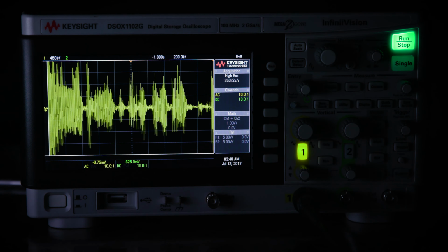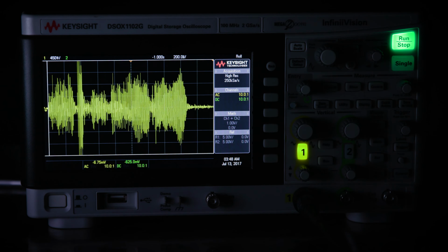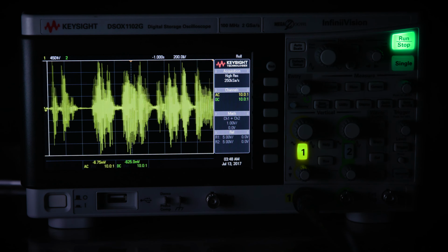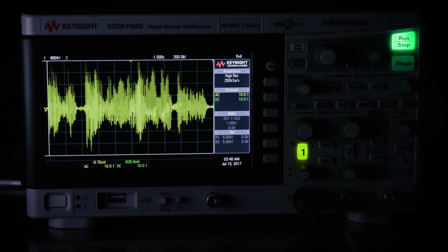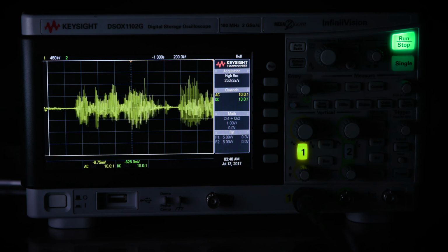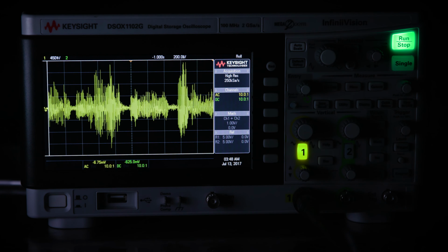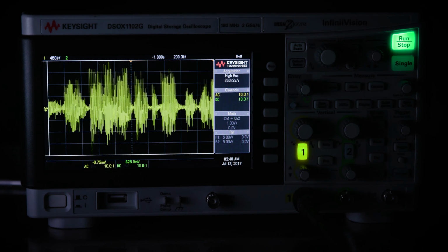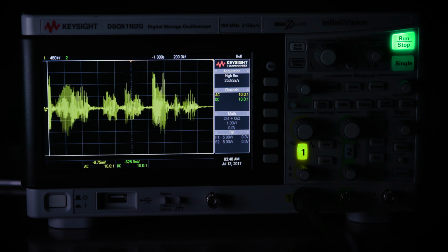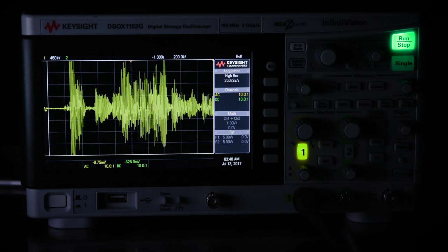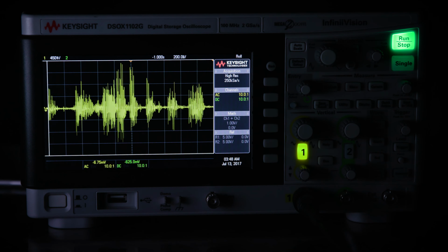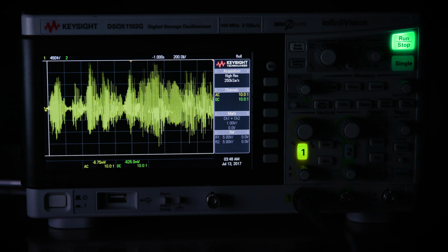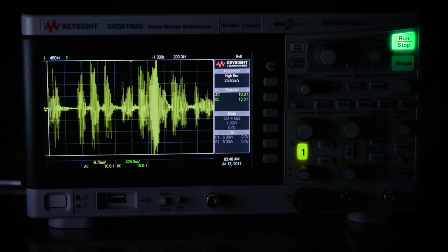You need a lot of adjustability, not only in the A to D converters, but in the samplers to get everything calibrated and aligned, because anything that you don't get lined up, let's say the Q levels of one A to D converter are higher than the other. So you've got one that's high and then 3 that are low. Got a whole bit of noise, basically. You're going to see a repeating pattern of high, then low, then low, then low, and high. So you get frequency spurs, basically.